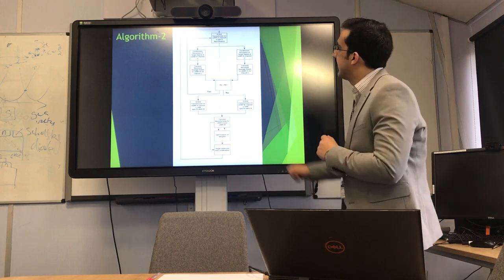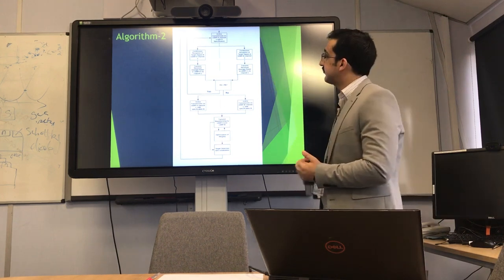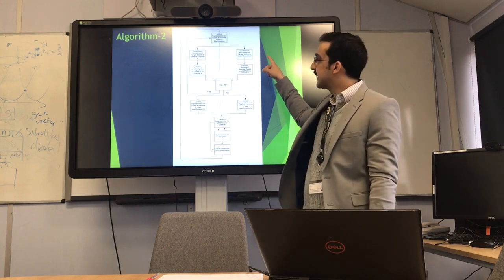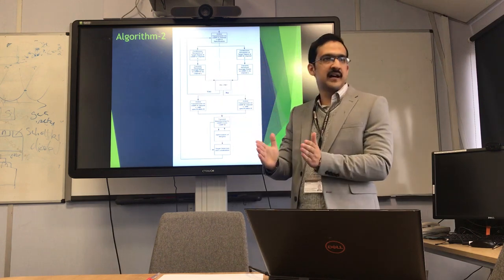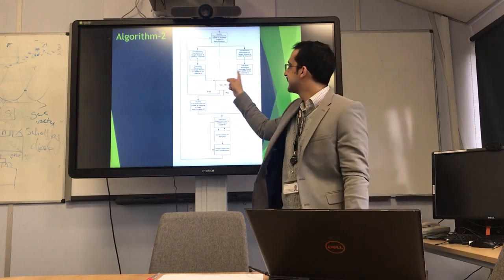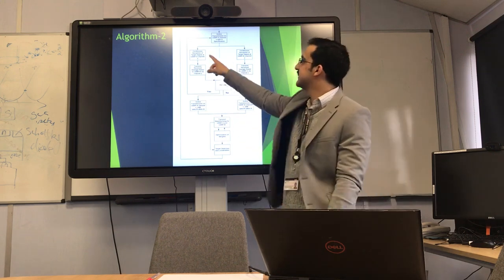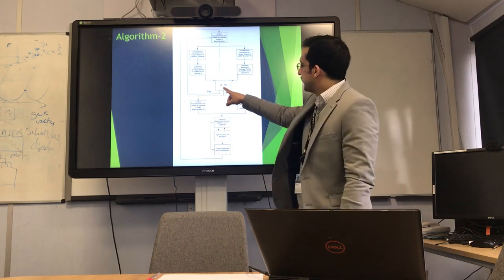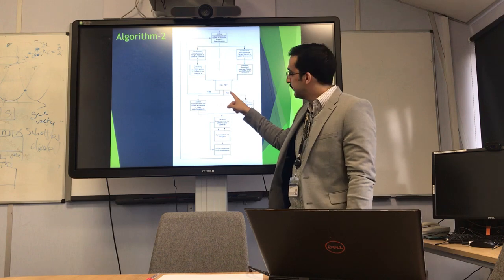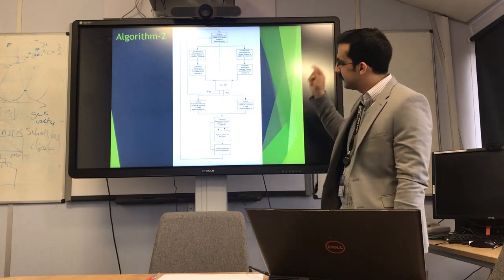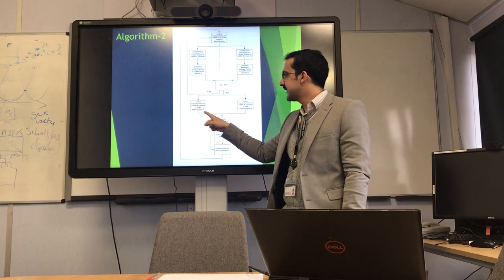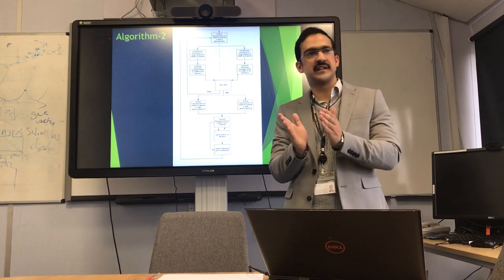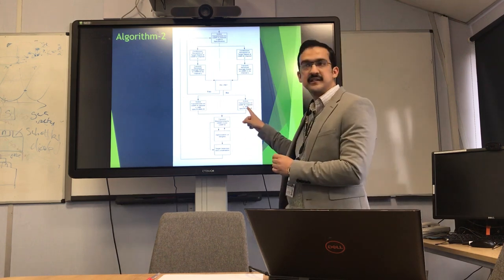In the second algorithm, there is active transmission on USRP-A. Again, the same setup: there's a continuous reception on USRP-A and there is continuous reception on USRP-B. Again, there is a radar-comm solution from the other channel, and there would not be crosstalk between these two because one channel would be doing the radar part and another channel would be doing the comm part. The power would be compared. If the power of A is greater than the power of B, the same loop would repeat. Otherwise, there's active transmission on USRP-A with the specification of B. So instead of switching off, USRP-A would keep on transmitting with the specifications of USRP-B.